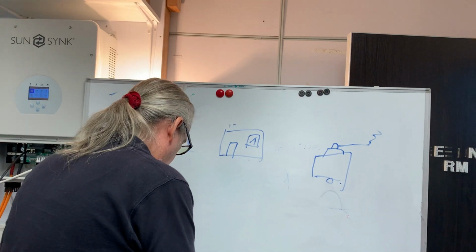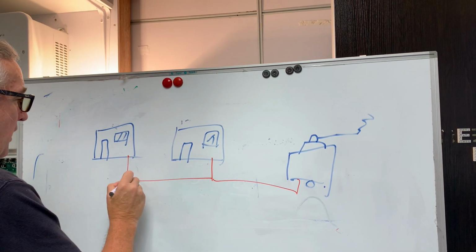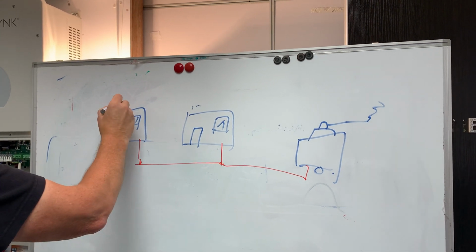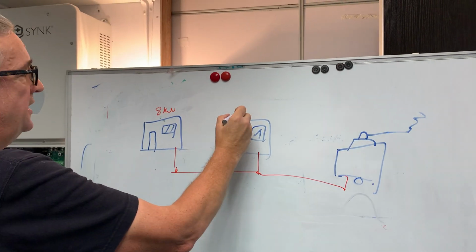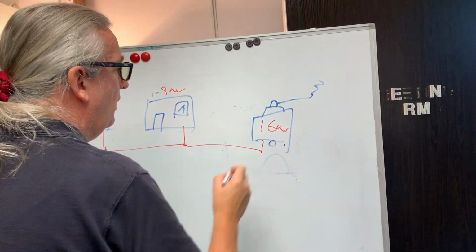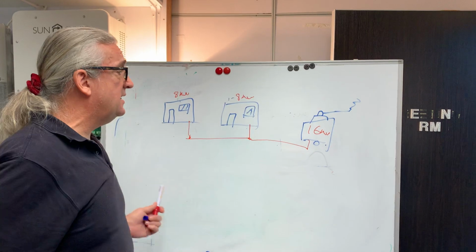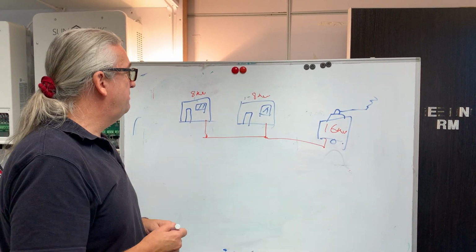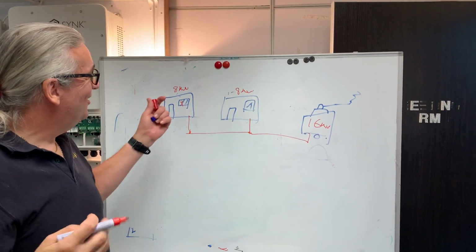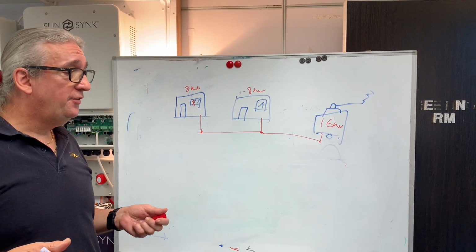The generator is sending the electricity here and here, connecting the power. Now, if one of these places has a peak demand of, say, 8 kilowatt, and this might have an 8 kilowatt peak demand, that means the generator's got to be 16 kilowatt. I might have a security man inside, a little stick man, or I might have people working at night, or I might just have traffic lights on the site, or often just leave the air conditioning running.